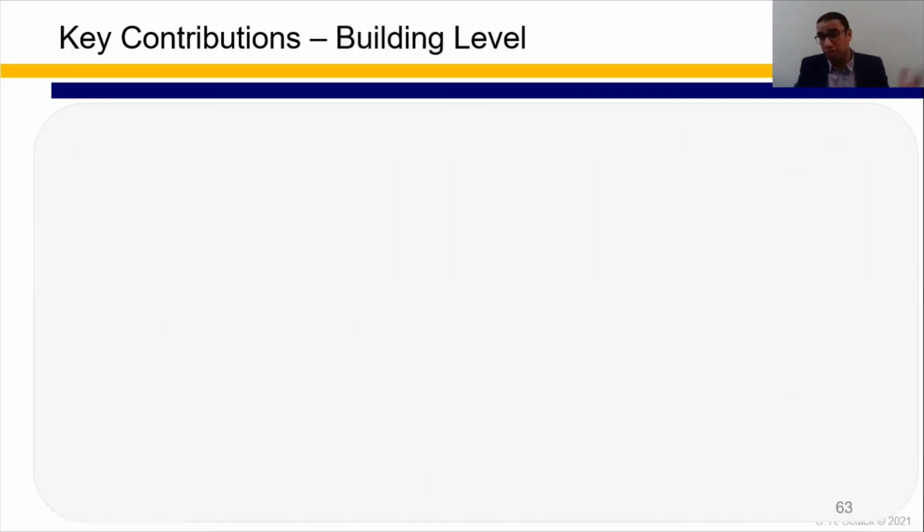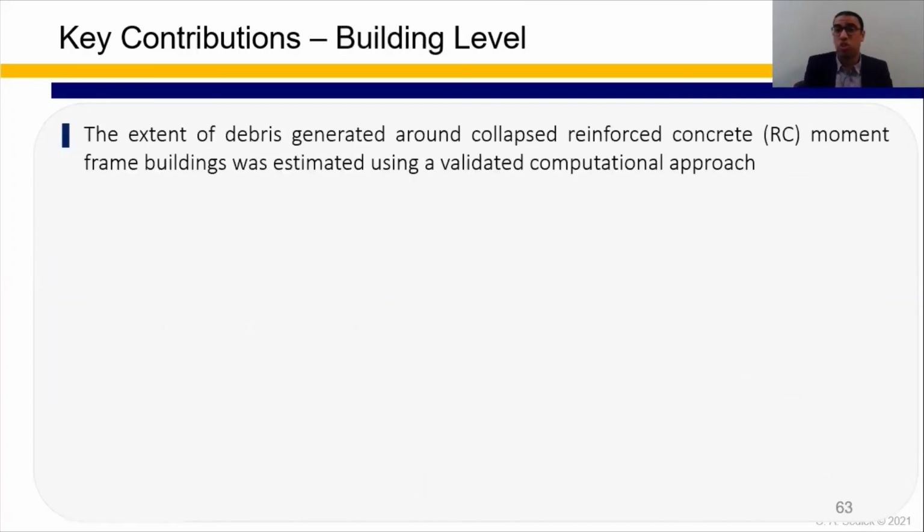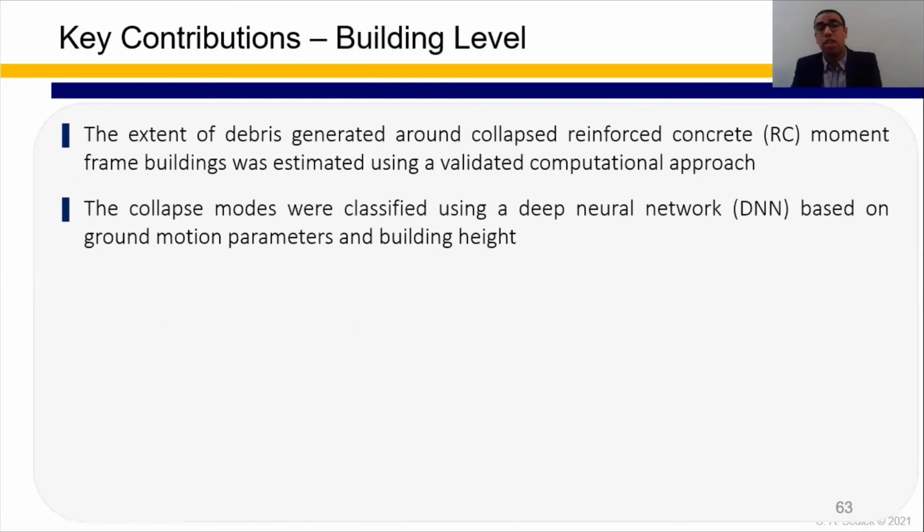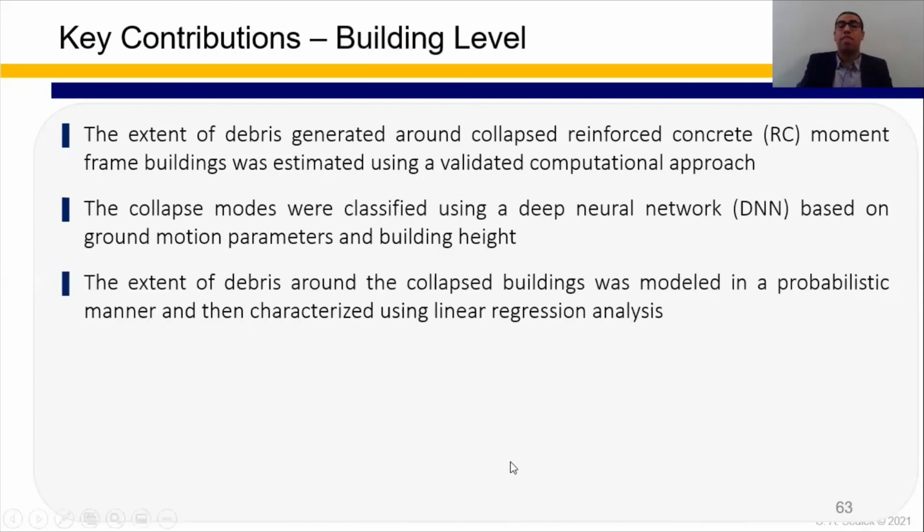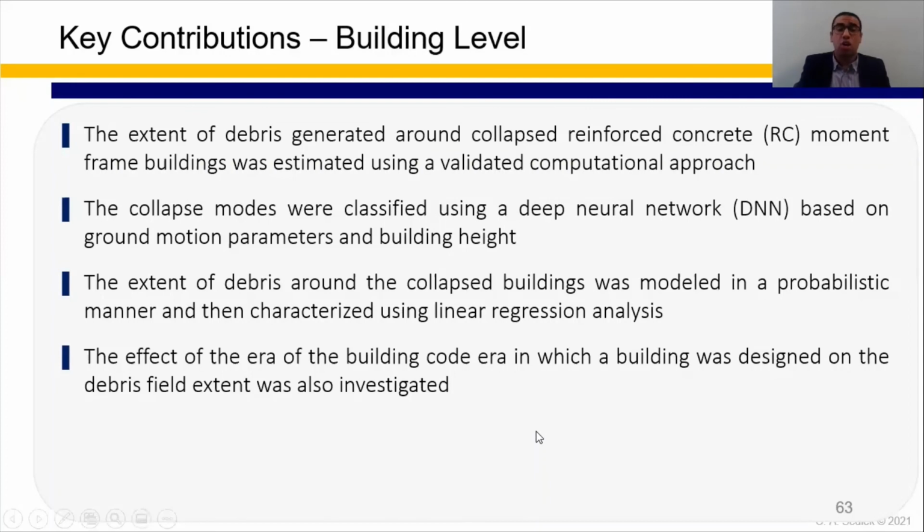On the building level, the seismic debris field generated from reinforced concrete moment frame buildings was estimated using a validated computational approach. The collapse modes were classified using a deep neural network, and the extent of debris was modeled in a probabilistic manner and characterized using linear regression analysis. Also, the effect of the era of the building code was studied on the debris field extent.